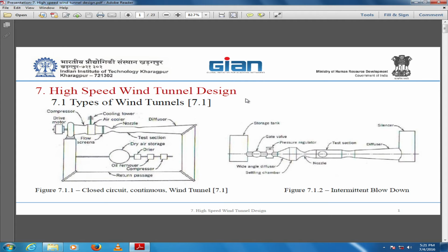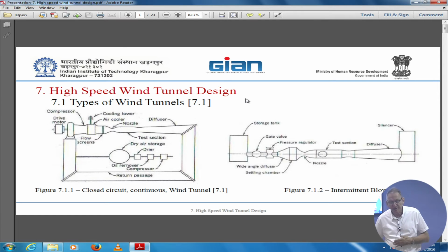And always you have extra power to start the tunnel, or you can reduce and start the tunnel with lower back pressure, whereas in the closed circuit it's only one route. You start accelerating the fan and you will get your starting load at whatever you have. Unless you are doing some procedure that will cost you a lot, I mean, starting with low pressure and then increasing.